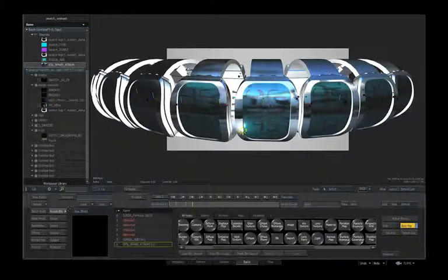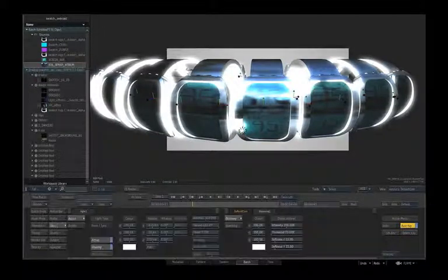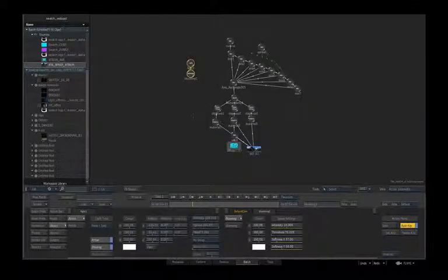I want to just add some refined lighting. Well, actually, we've got a light in the scene, but let's add some blooming to it. So this is a technique where we can start to create 3D glow, maybe even just a nice softened-out diffuse glow if we wanted, or a tighter one if we want. And then even more on top of that if we wanted, let's just go easy on our bloom for now, as I wanted to add in a streaking effect as well.